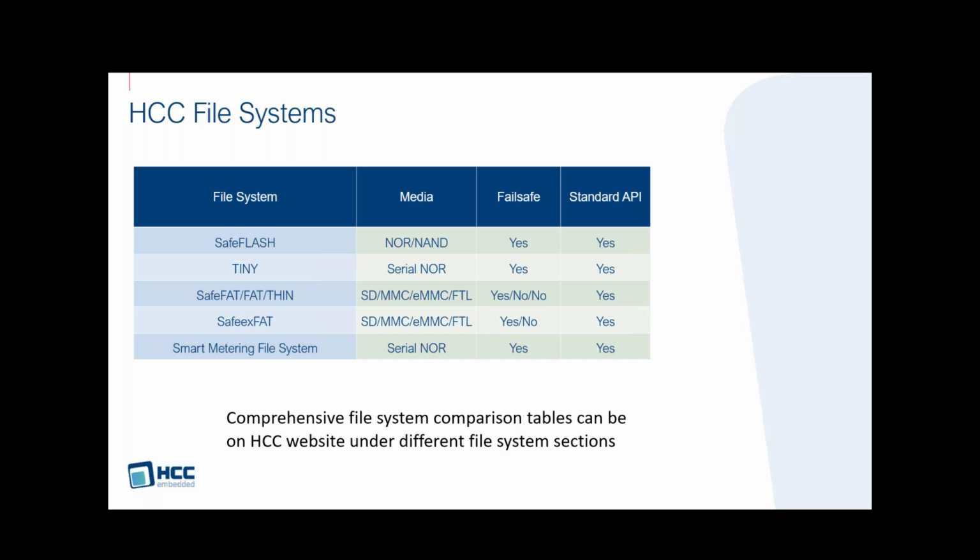This thing gets translated through the file system, maybe through a translation layer, into several operations. If it's an SD card, then internally that will become several operations, because an SD card is just a flash translation layer and NAND flash. And that becomes a lot of operations. By focusing on this particular application, we're able to create databases directly onto serial flash, skipping these layers of management